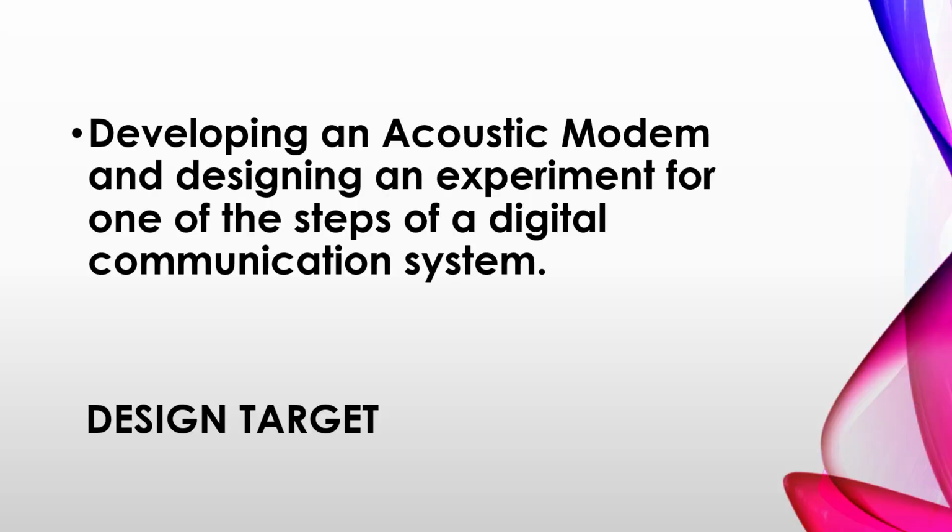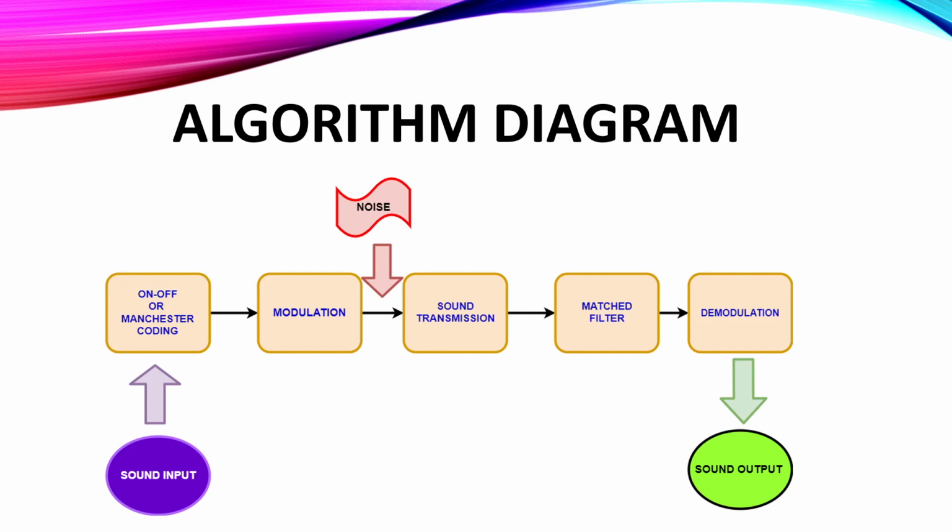The design target of this project is developing an acoustic modem and designing an experiment for one of the steps of a digital communication system. So we wanted to show the algorithm diagram. We input sound to our code, and we encode it with pulse shaping. We chose Manchester pulse shaping because it's more effective.